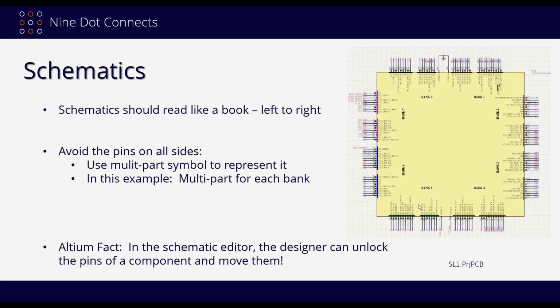Again, going back to this concept that schematics should read like books from left to right, this is another thing that's been developing over almost the last 2 decades. When I first started in the industry in the early 90s, I saw a lot of DIP packages. The DIP packages were easy enough because they had pins on one side and pins on the other side. And then pretty soon these quad flat packs were coming out, these FPGAs were coming out, and of course the BGAs were coming out,